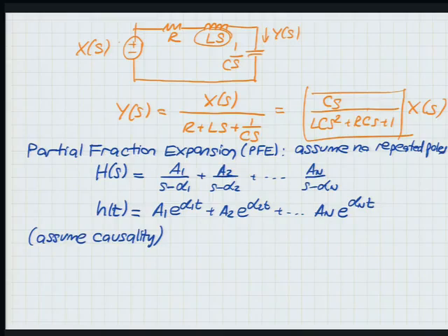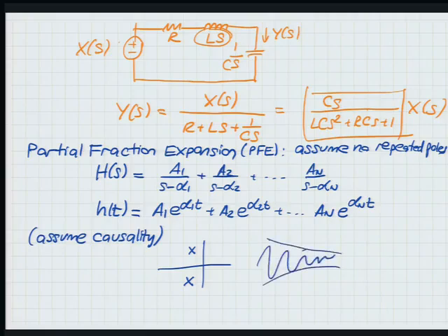So a system, let's say a system with poles that are here and here. Negative real parts, but they are complex. So how does this system react to an impulse or anything else? What kind of reaction is that? There will be oscillations, but it will be decaying, right?